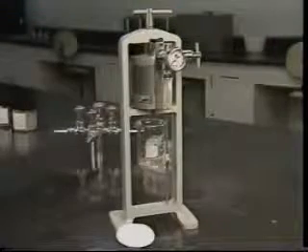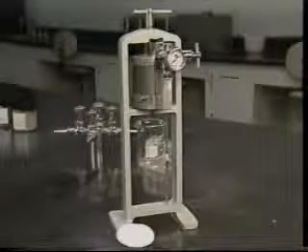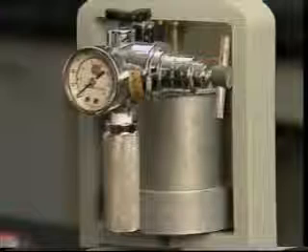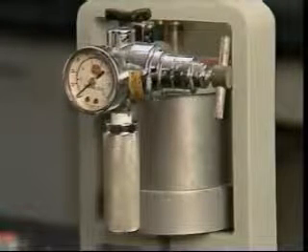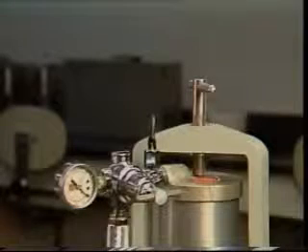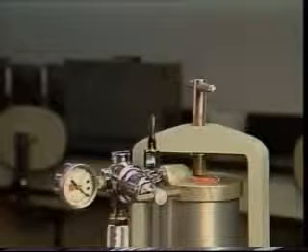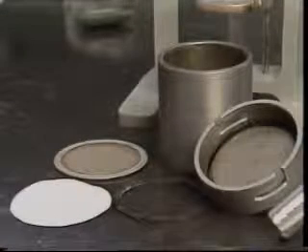The filtration and filter cake building capabilities of the drilling fluid are determined by means of a standard filter press. This unit consists of a mud reservoir mounted in a frame, a filtering medium, a graduated cylinder for catching the filtrate, and a source of gas pressure. The test requires 100 psi for 30 minutes. It may be supplied from a high-pressure air system, from compressed gas cylinders, or from CO2 cartridges. The test is conducted at surface temperature with filtrate collected in the cylinder and the amount recorded as cubic centimeters per 30 minutes. The test is performed as follows.